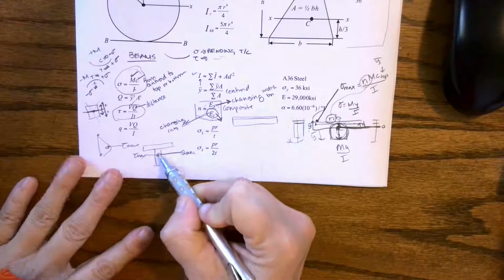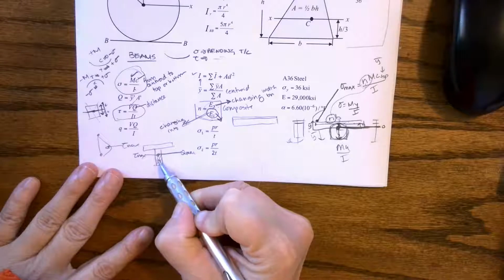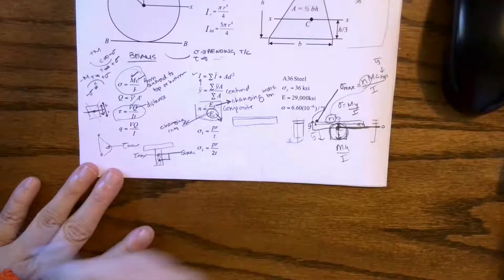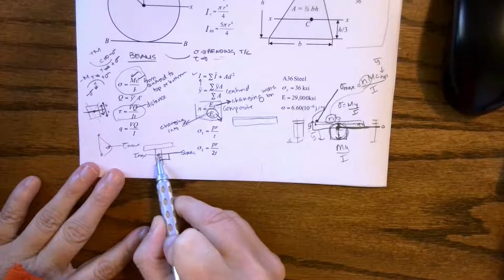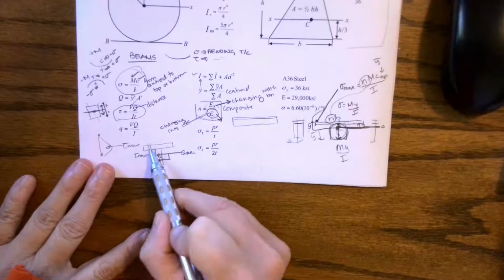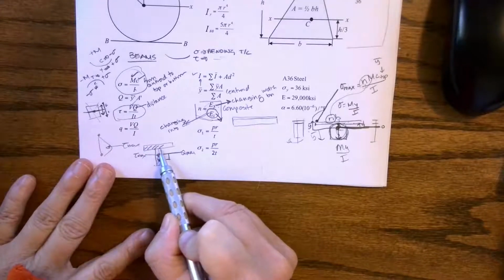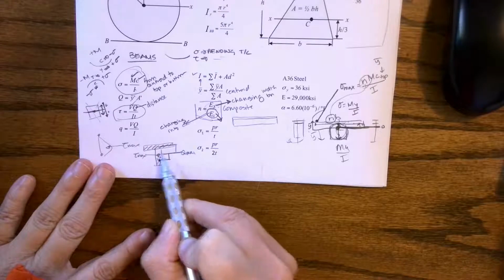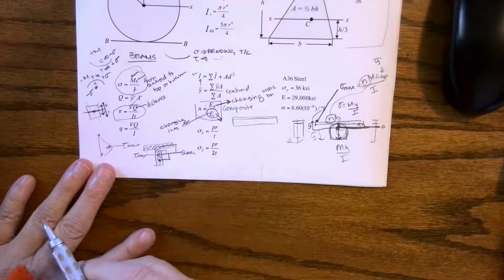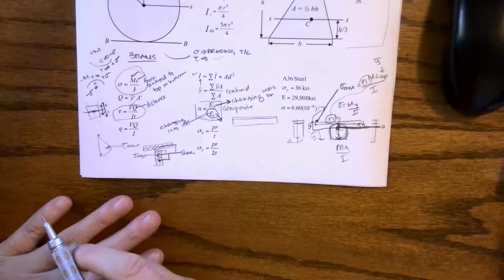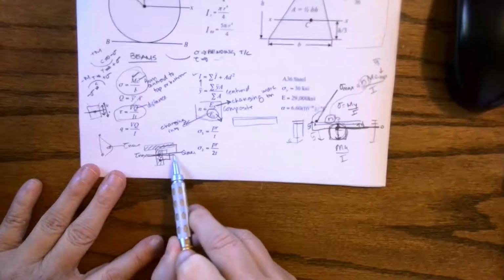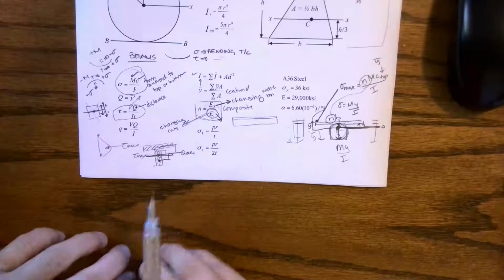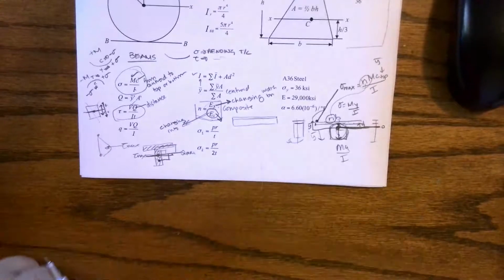And I can either go to the bottom, so I could look at all of this, that's my area, and then my Y is from the centroid of this area to the centroid of the whole. Or I could look up here. I could take all of this area times this centroid plus this area times this centroid. It's super simple. We can divide up our areas and just multiply by centroids, always back to the centroid of the whole. We always work with centroids to centroids to centroids, okay?